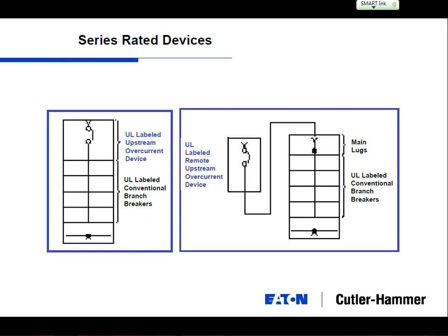And I believe when you put your arc flash label, it will take it on the line side, not the load side. Yeah, you have to put your PPE on it even if it's open, because you could reach the line side. So that's what we say when you put it outside: this is dead. Lock it, tag it, and work on it. Absolutely. Every piece of equipment now has to have an arc flash label. It shows you the energy and what type of personal protective equipment you need to wear. And the only thing we look at when we're providing analysis and putting stickers on is the line side of that circuit breaker.